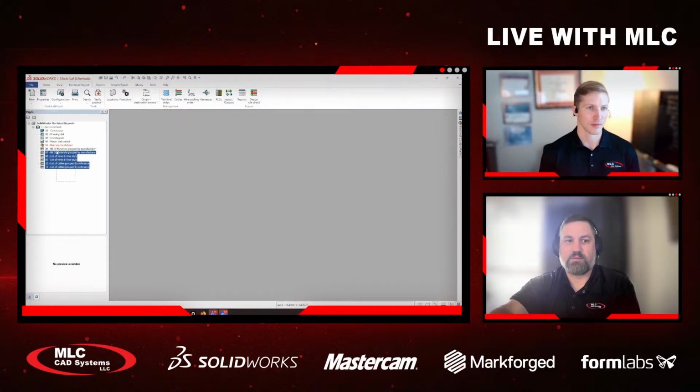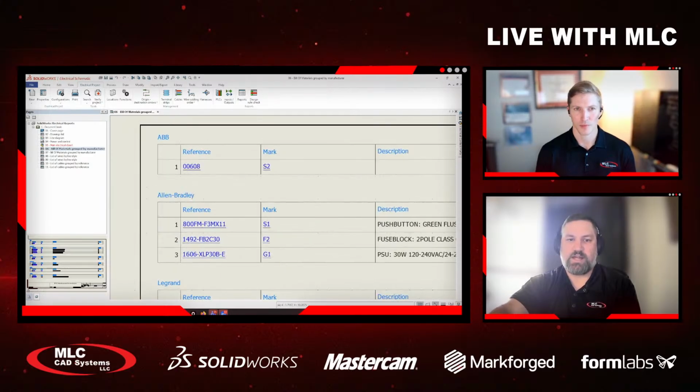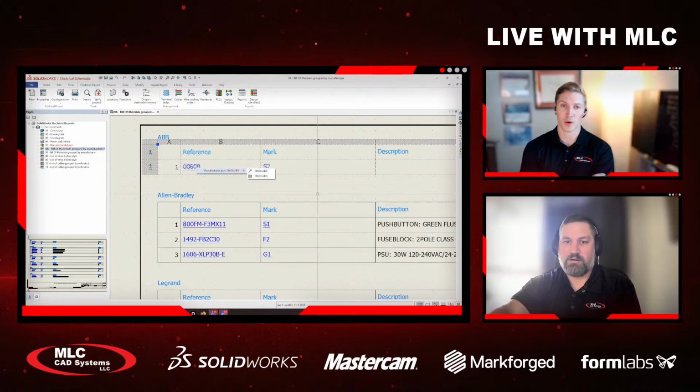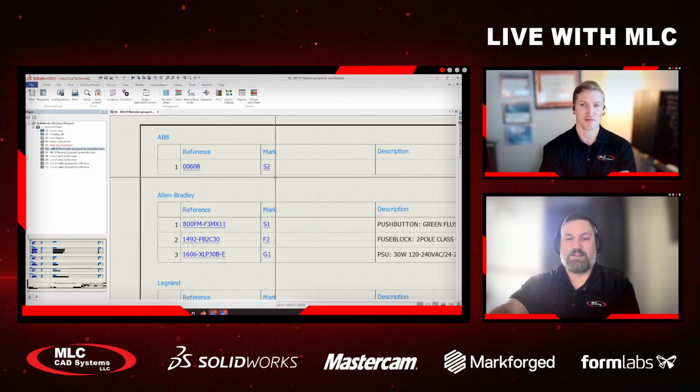You'll see that we have a number of report pages that have been added to our project. I'm going to go to this bill of materials and we're going to take a look at it. Now, this is put down on whatever template you have, so I would encourage you to have the correct title block for your reports. Now, if I zoom in, you'll see it says ABB and then Allen Bradley, and then it has a reference, which is part number. If you were to right click on it, you can go to that specific manufacturer part. Oh, that's nice. So it's like a hyperlink. It's like a cross-reference. That's exactly right.